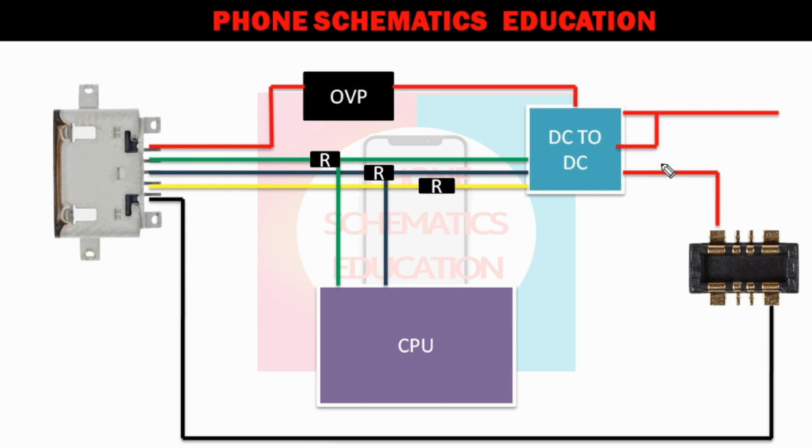I'm telling you again. When you connect the OTG, the requirement is near about 5 volt. Right? Now the OTG is connected, so there is no charger. Now your phone runs in battery mode. So there is a MOSFET working in reverse. Your phone runs on the battery. Now, the same voltage goes through a MOSFET back to the V bus line. How?